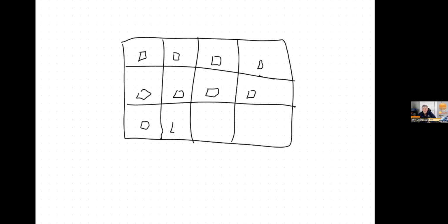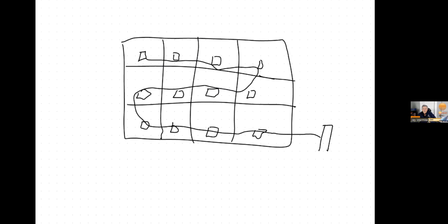So all these microinverters are connected together. My string, which is actually called a branch circuit, would connect all of these together. Then it would go not to an inverter, because these are all inverters, but to an AC disconnect to turn it off. And then it would go to your service panel like that.